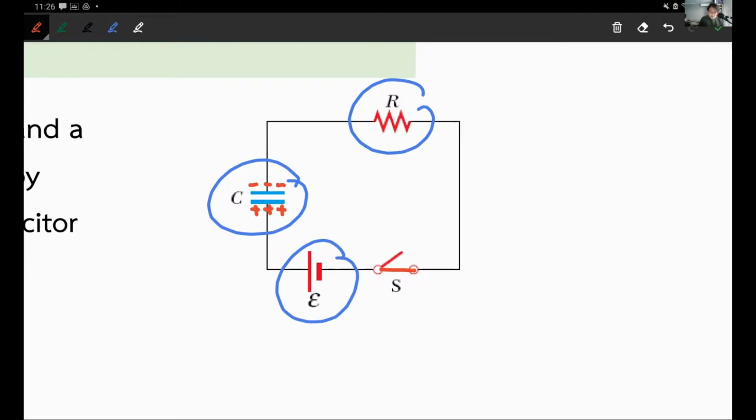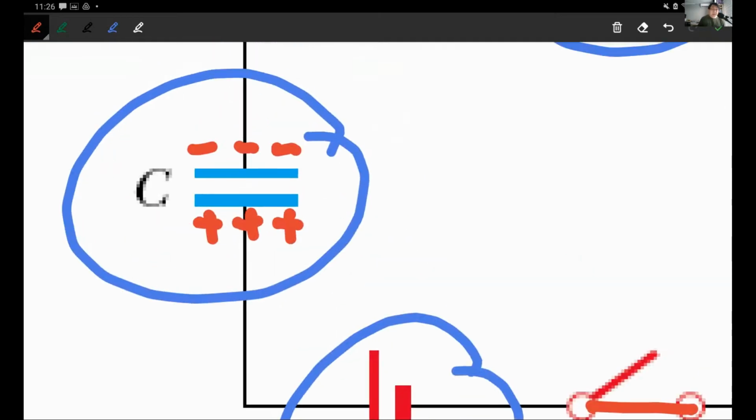But now, you can think of the plate on the capacitor to be a room. When you have the current flow into the room, the next charge that tries to enter the room will have a harder time entering. With me? Why? Because the same types of charge will repel each other. There is a Coulomb repulsion between the same type of charge. So when there are already some charges in the room, the new charge that tries to enter the room will get pushed back a bit. So it's getting harder to get into the room the more charges are in the room.